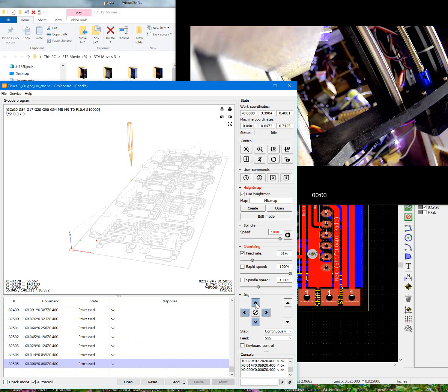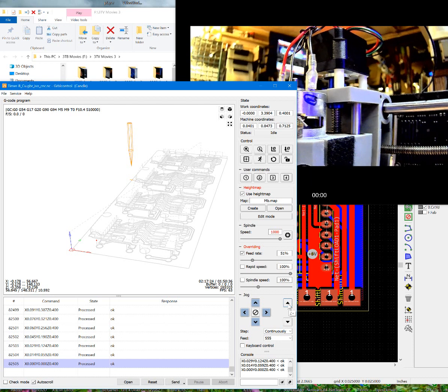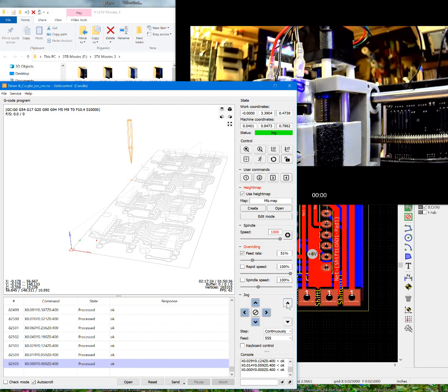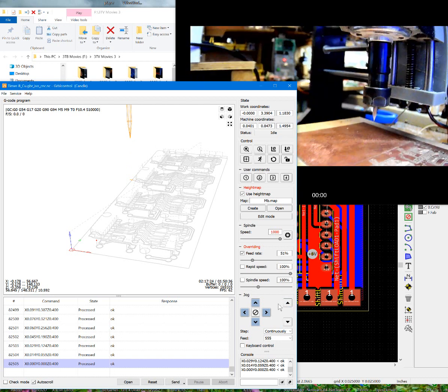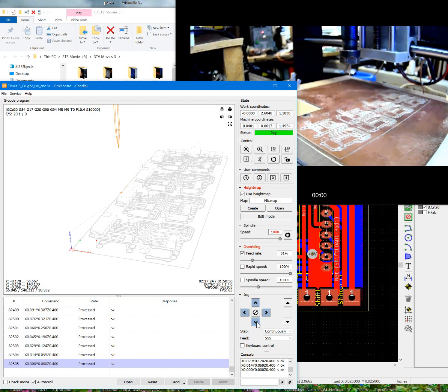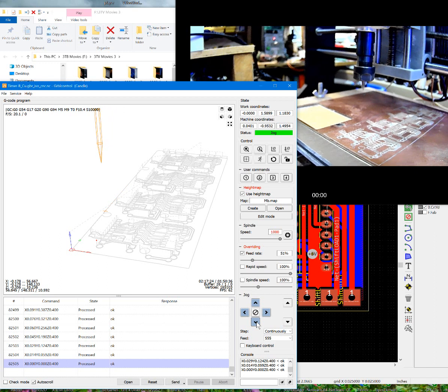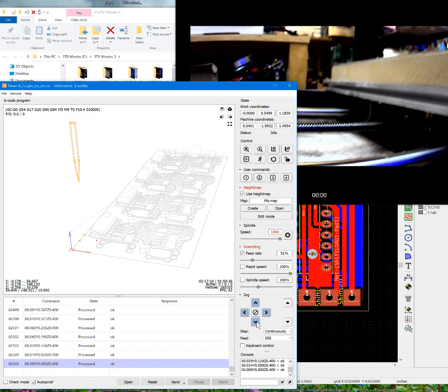But anyway, let's go ahead and get set up for the next step, which is to do a route. So I'm going to go ahead and, like I said, the bit is up there quite a ways. Well, let me go ahead and raise the Z a little bit. Okay, that's good enough. So I can change the bit. Move it forward. That always helps. That's enough.